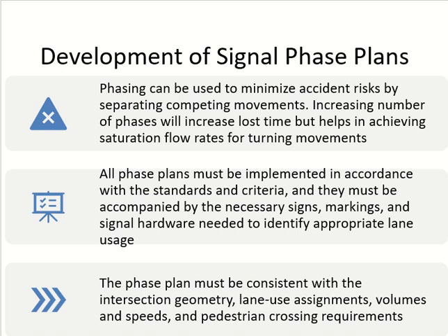The last point you have to keep in mind is the intersection geometry and the volume requirements. You may have a T intersection. You have intersections where the roads are not meeting at right angles. You have intersections where maybe more than two roads are meeting. You have more than 4 directions. So you have to keep all these things in mind while you are deciding the phasing plan and the volume as well. And we talked about number of lanes, right? So I want to provide an extra lane, but there is no space. What should I do? I have to change my phasing plan.